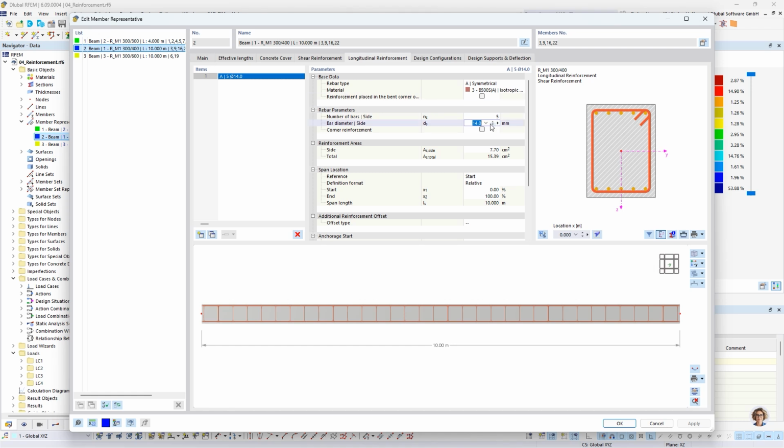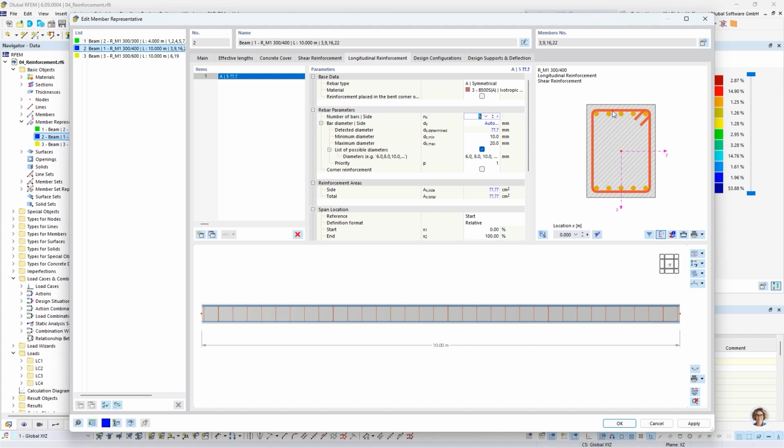For the representative number 2, we want to automatically design the diameter. So we want to put inside 5 members in the range of 10 up to 20 millimeters of size. So whenever it reaches the maximum, it stops, of course, to input more members or thicker diameter. So you should see in the results that then the design is not fulfilled. So you can later on adjust, of course, these boundaries in order to let the program fully determine the amount of members. So you see what you can enter in here.